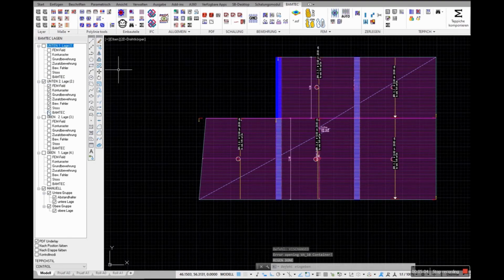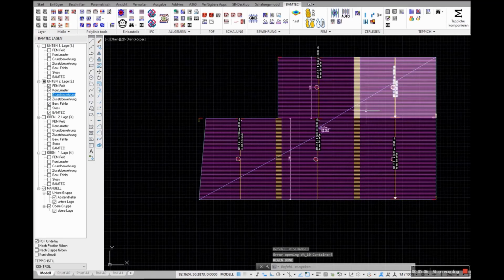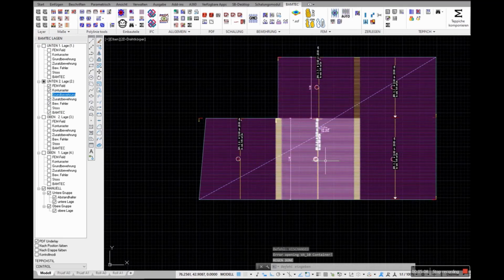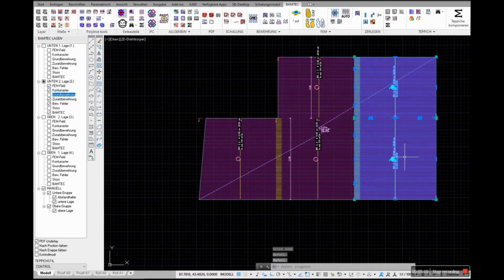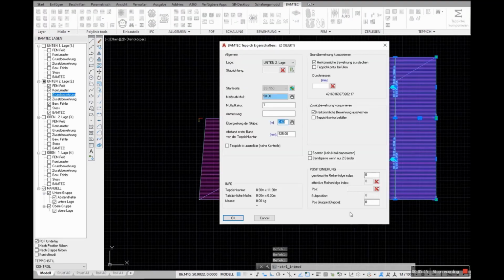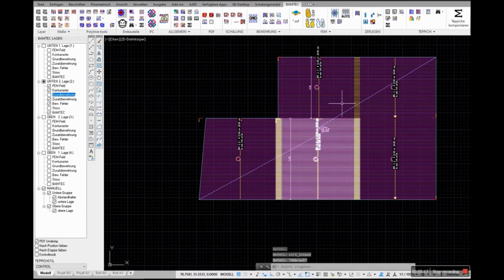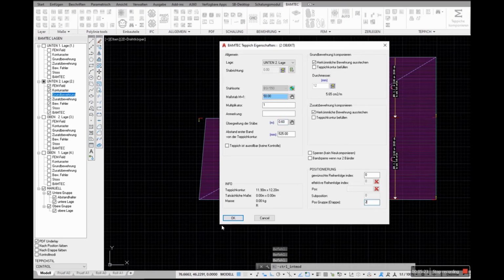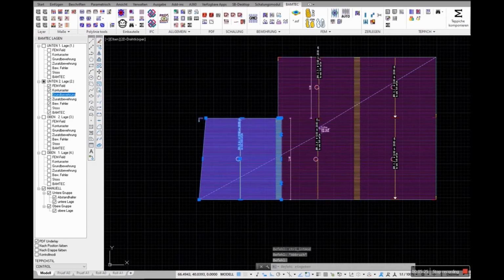Very briefly, now we go into the second layer where we have different bar diameters. We've got 12mm bars in the second layer. You can see that immediately. You've got a different color of the bars. The overlap and the joint areas can be colored as well for easier testing, easier review. Once again, the sequence of operations is detailed.